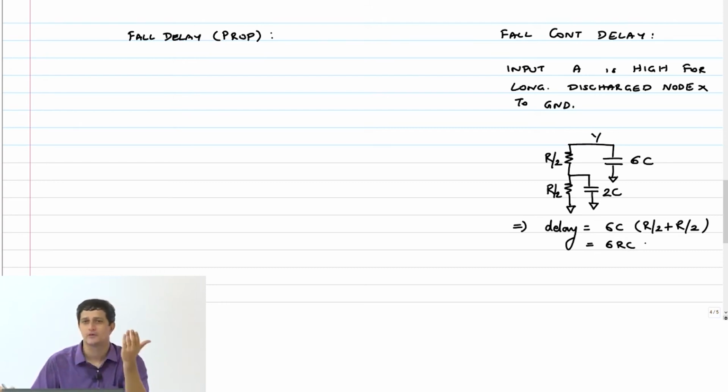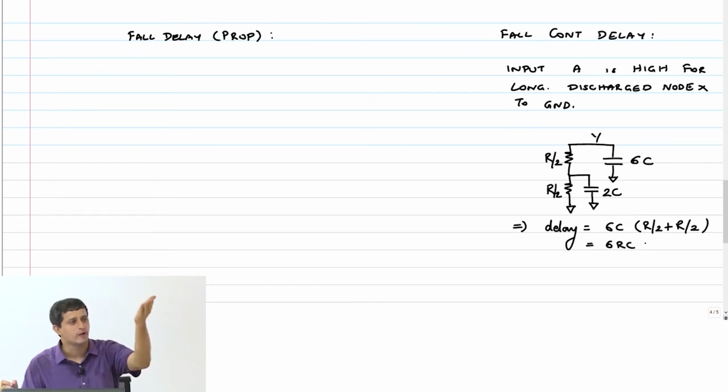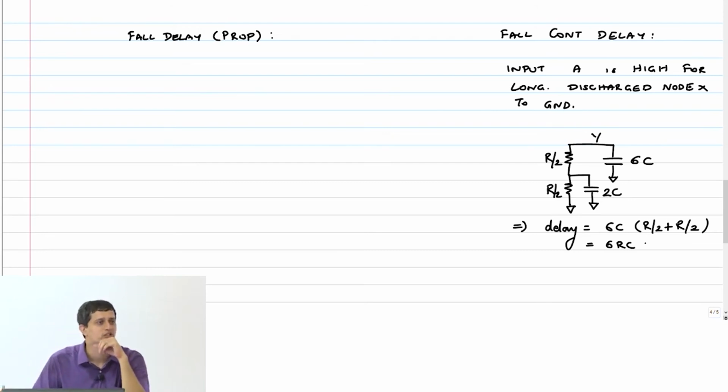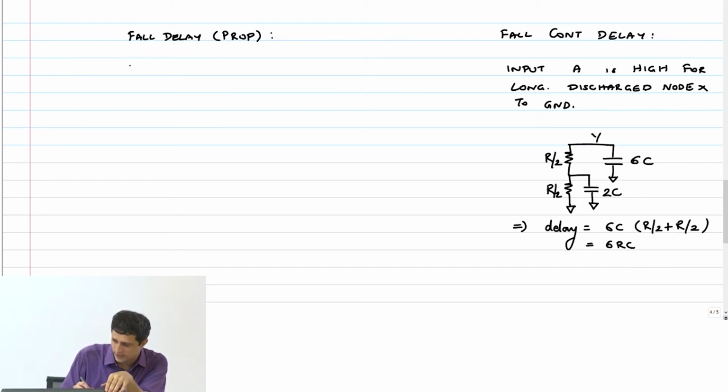You apply the same thing that I gave in the quiz. Initial condition where instead of 3 by 4 VDD, I said you make that ground. That capacitance term will just vanish, right? But the on-path resistances will still come for the other guys, correct? And therefore that becomes 6 RC, okay?